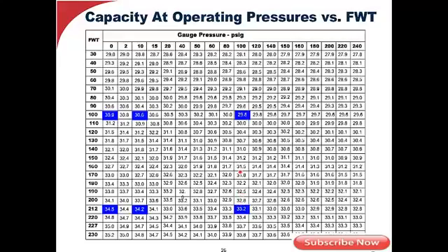That's why that is. But look at this drop because of the 100 pound operating pressure and 100 degree feed water. I'm down to 29.8. So when I thought I was going to get 34.5, I'm down to less than 30 pounds per hour, per boiler horsepower. The importance: operating pressure, feed water.